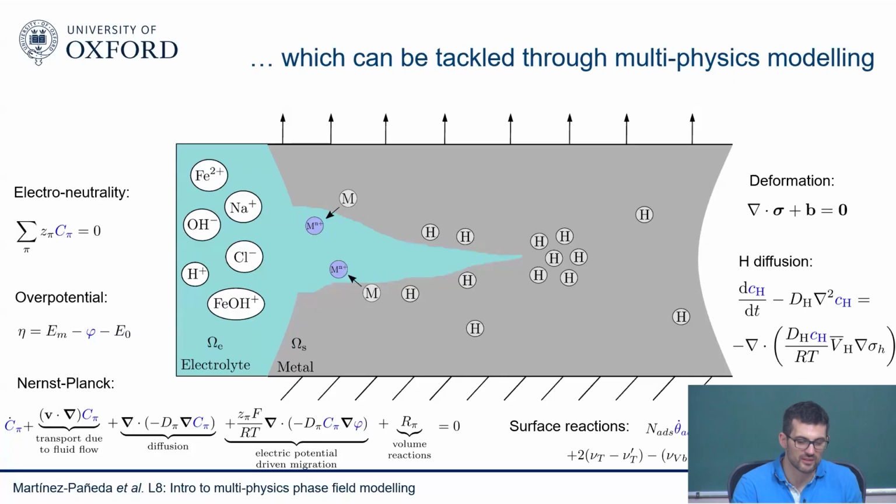There's another element of this that complicates things further. The other element is that this defect that you're seeing here evolves in time. So it's not stationary, it's not going to be sitting there, it's going to evolve in time. Whether you have pitting or cracking due to mechanical rupture or another dissolution, this thing is going to change morphology and shape. It is going to evolve in time. And how it changes in time is critical.